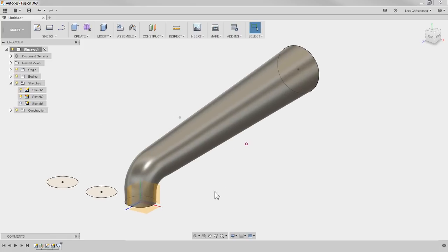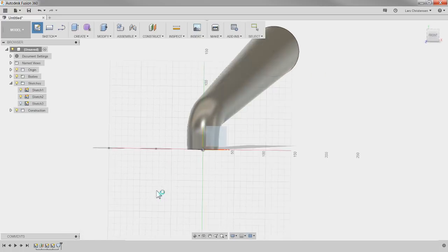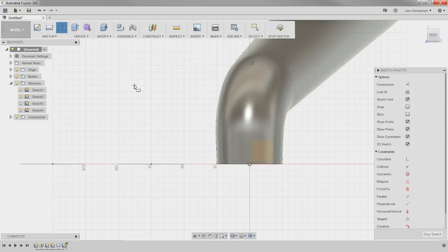And hopefully this makes sense. So I'm going to repeat what I just did before. I'm going to create a new sketch on that front plane where my circles are. So just hit alpha line. Let me just sketch a line out here. I'm going to make it 50. When I hit the tab key, I get a lock next to the 50. Actually, if I hit the tab key or the enter key again, then it gets locked in and I get that vertical relationship. You could just insert that manually if you want to.